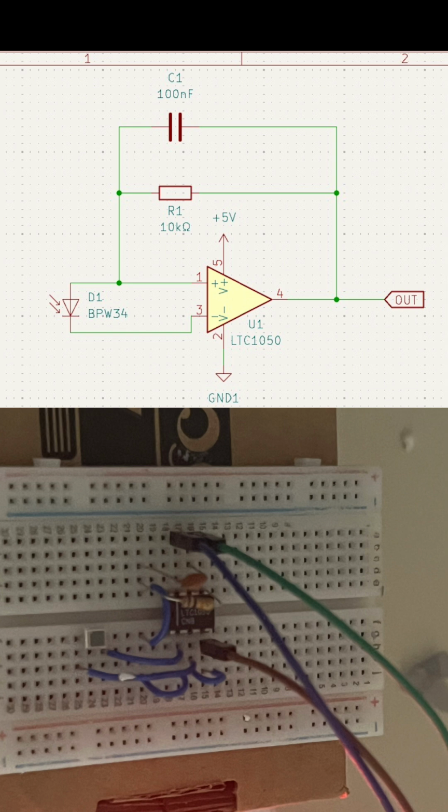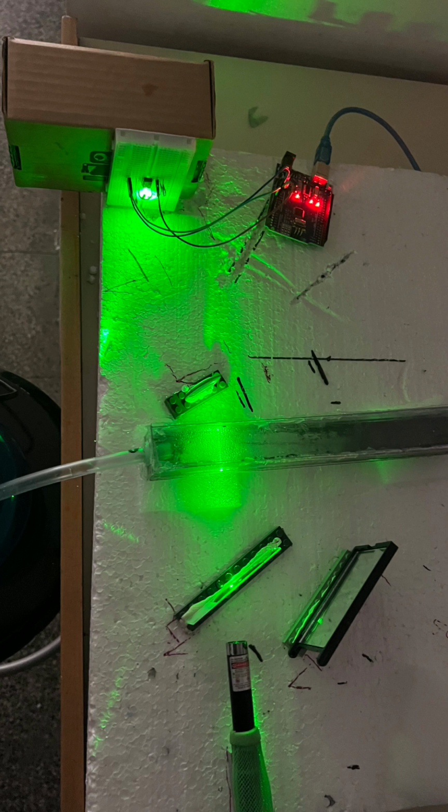We constructed the breadboard circuit with connecting cables, signal amplifier, 10,000 ohm resistor, 100 nanofarad capacitor, photodiode, and some jumper cables. MATLAB and Arduino code scripts were used to measure signals, Doppler frequency shift, and light intensity. We put all the setup together and put the rectangular prism on the measuring volume. We put a converging lens after the rectangular prism to focus the two beams at another point. The other intersection point will be the place where the photodiode will be placed.